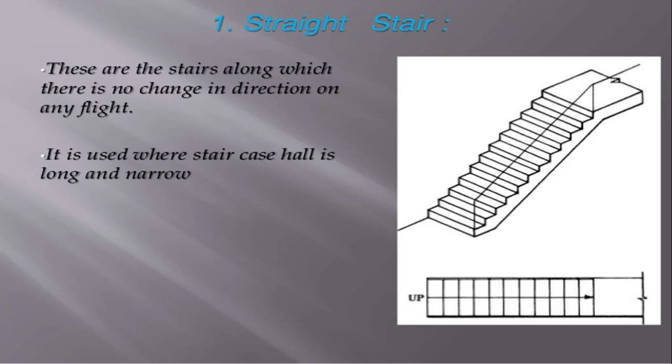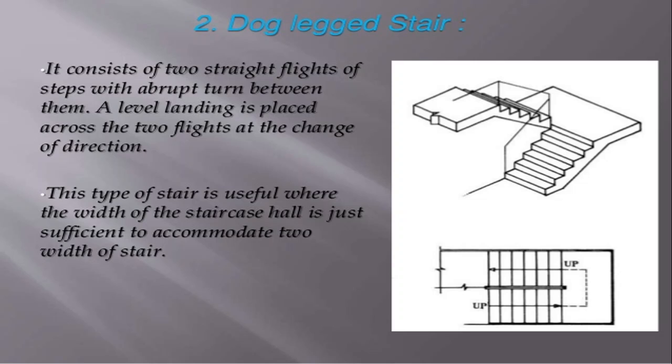If your hall is very long and narrow, you don't need to turn, or no need of change in direction of stairs on any flight. So you can directly have this long and narrow straight staircase. Okay. Next, dogleg staircase.